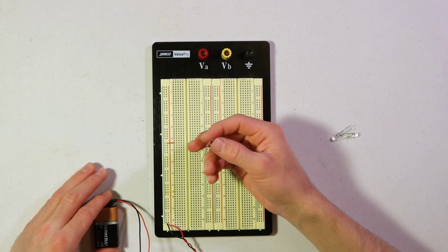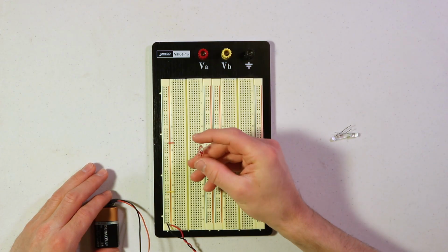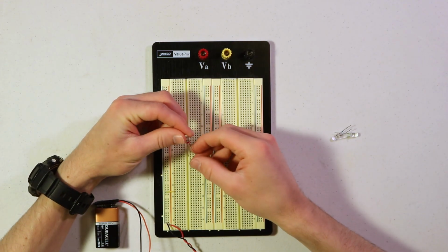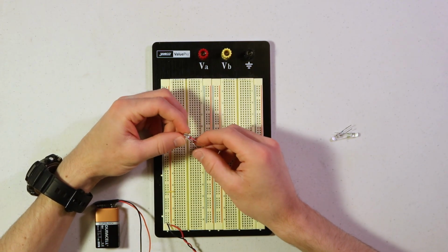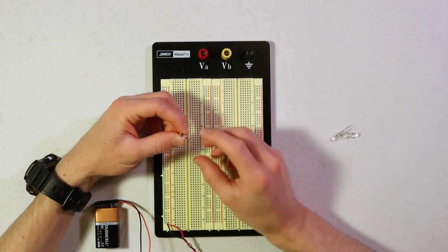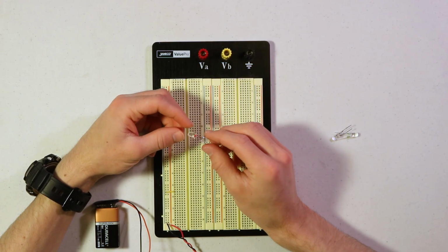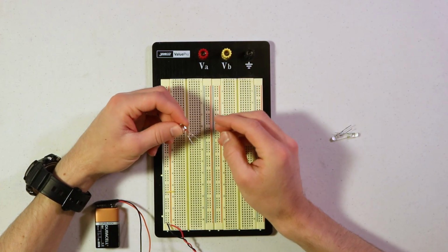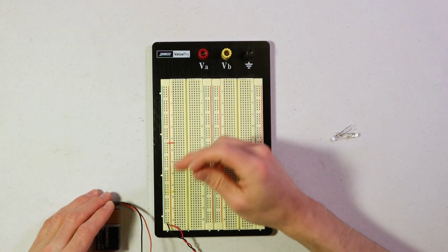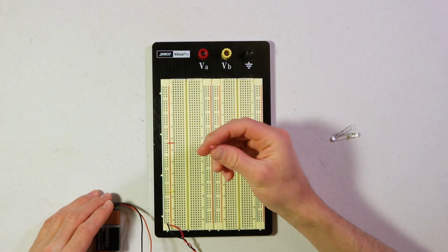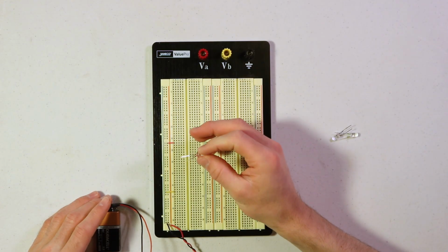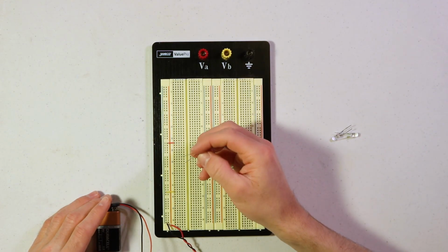Whenever you have an LED in a circuit, you always want to have a resistor in series with it. The reason for that is if you don't, then too much current can flow through the LED and burn it out. If you exceed 20 milliamps, which is normally a good rule of thumb for an LED, then the LED will get really bright and then burn out and it won't work anymore. So you just want to choose your resistor so that the voltage you're applying across both of them with the LED is okay. It won't flow too much current through it, and it keeps it within that 20 milliamp range and you'll be fine.